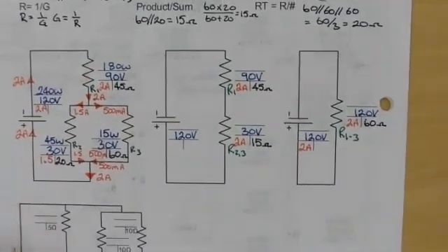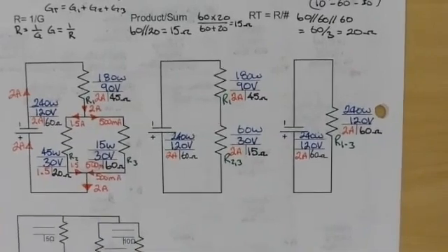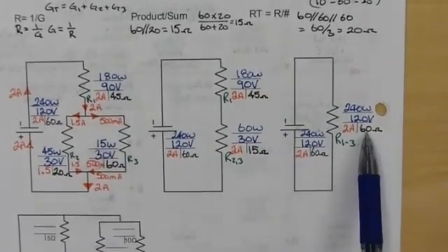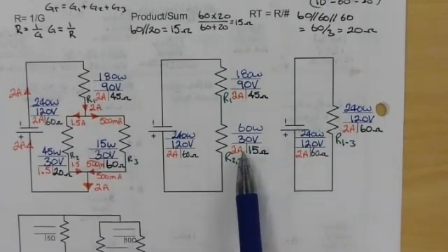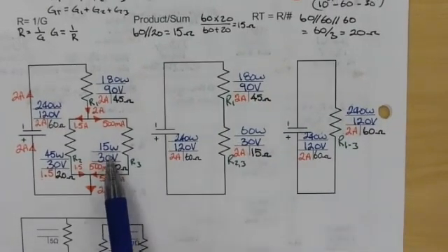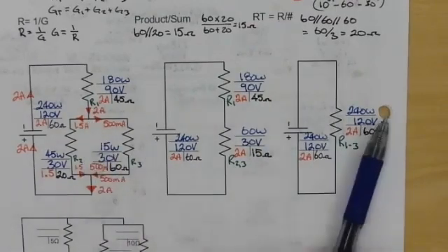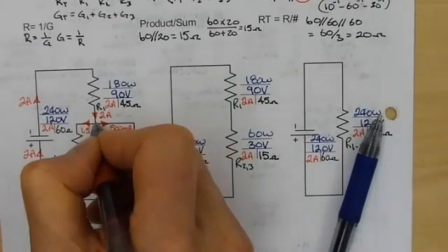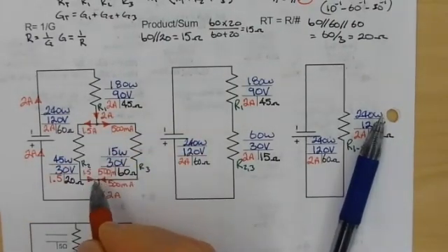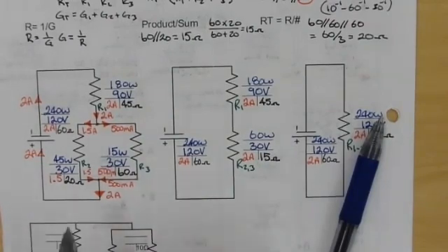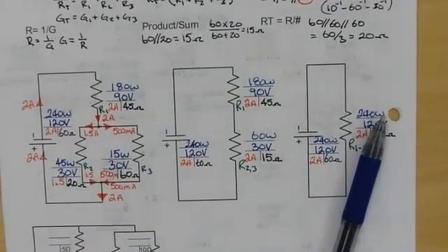So there's our circuit. So we went all the way up to here. We came back, moved our current in here to the series circuit. Found 30 volts across here, and we brought our 30 volts from there in parallel, so same voltage. That and the resistance found the current from the wattage. Found the current node. Laws here, Kirchhoff's current node: current into a node has to equal the current out of a node. So just coming in, coming out. All of our wattages add up, voltages add up.